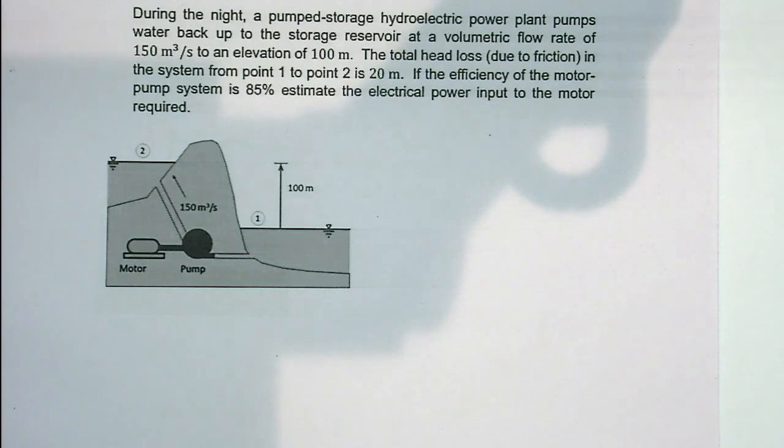But what we could do is assume the flow is steady, which means the velocity is the same along the pipe, and also adiabatic because of no heat transfer, and incompressible because it is water. So from point 1 to 2, it has friction loss, so we couldn't use the Bernoulli equation, right? But we can use the energy equation instead.